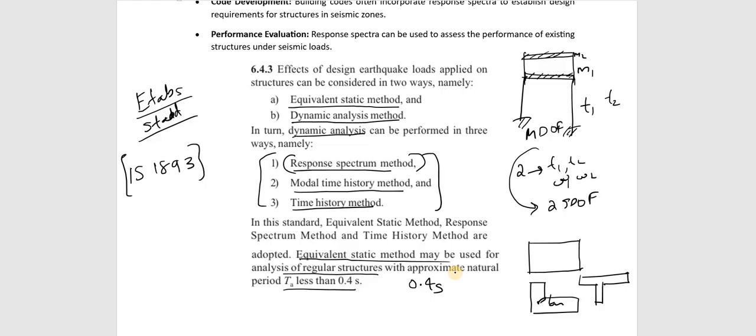In the plan there will be irregularity. Or sometimes in the elevation. The elevation may be, this is a normal structure, the elevation. But sometimes some parts of the building may be at a lower level compared to the other part, like that. So structures like these are irregular structures. In those structures, we will be following this type of dynamic method of analysis. And in that, our discussion will be mainly on response spectrum method.